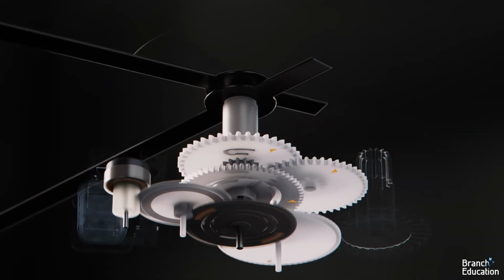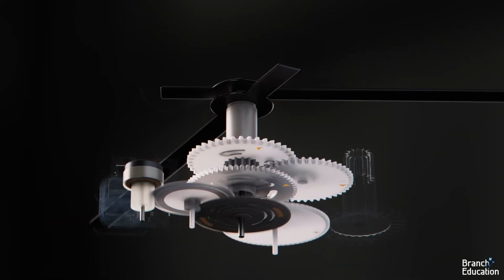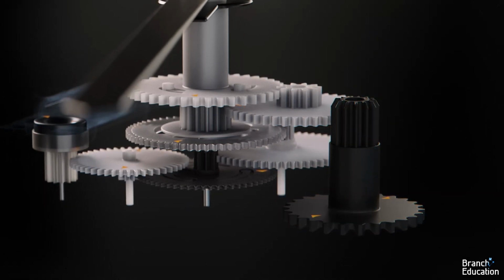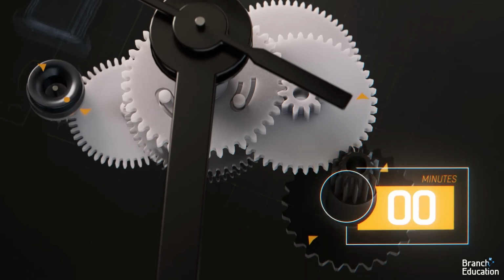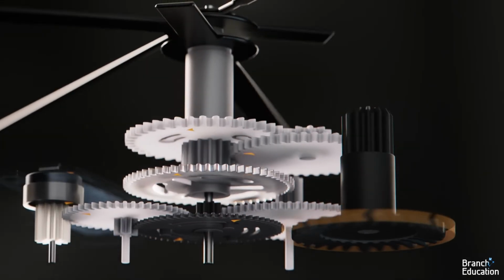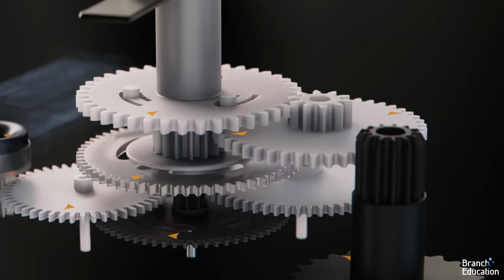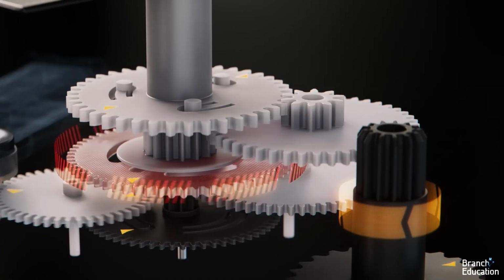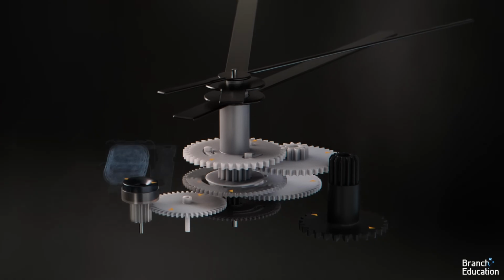As a result, we have 3 shafts rotating, to which the hands of the clock are mounted, each rotating at different speeds. The last gear is used to set the time, and interestingly, this gear has 13 teeth on it and rotates once every 69 minutes. As in the name, the time-setting gear directly rotates the minute and hour hands. However, the gear with the second hand doesn't move because the 2 parts of the compound gears slip from the high torque required to rotate the second hand 52 times per rotation of the time-setting gear.